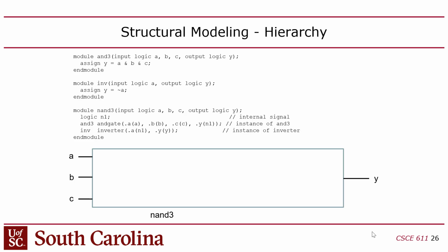The problem is that, as I mentioned on Monday, these files form a design hierarchy. But if you just have the files, you have no idea what the design hierarchy is, because there's nothing in the files or the names of the files that imply what the hierarchy is other than the internal contents of the structure, right? So if you go to GitHub and download a hardware design that has 100 Verilog files, you're not going to know which one is the top level file and which ones are the leaf files. Unfortunately, the only way to do that is to look inside.